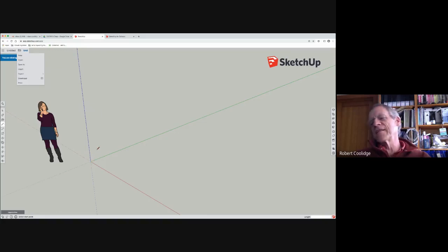In SketchUp terminology, we're in a 3D world, and you're looking at the origin with 3 axes, which you might usually refer to as X, Y, Z. In SketchUp, they're red, green, blue. You'll see that discussed sometimes as the red direction, the green direction. That's their terminology for these axes directions. The solid one is positive. The dotted line is negative in each of those directions.